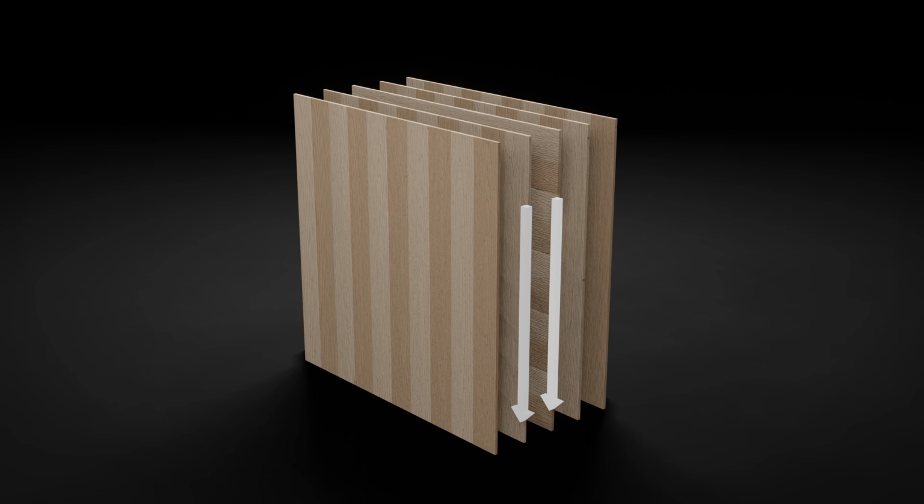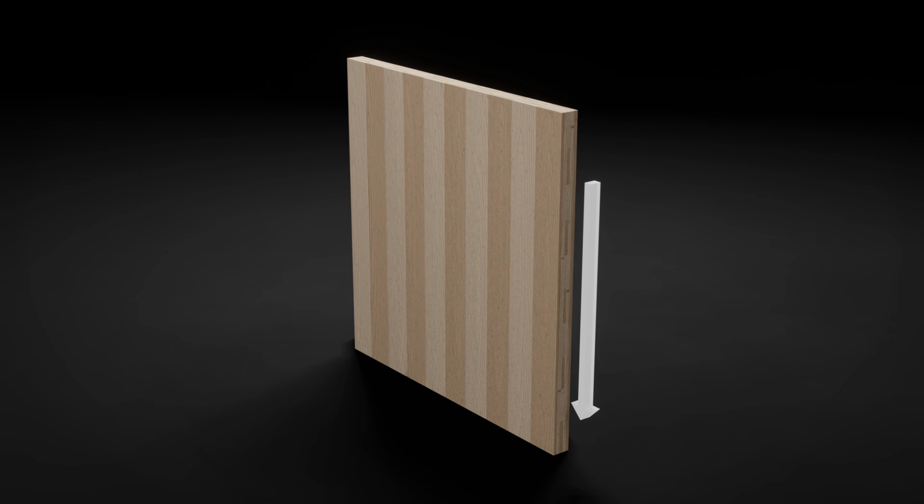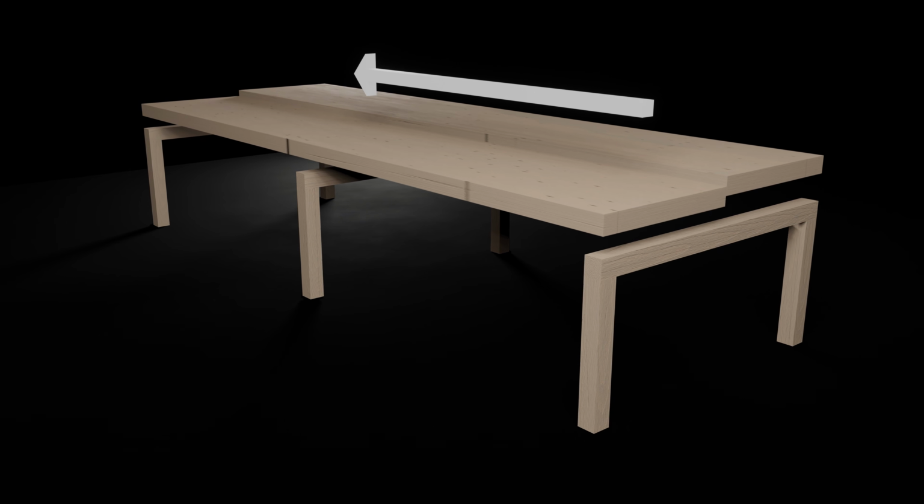For example, the outer two layers of CLT panels can have two parallel layers instead of perpendicular ones. In CLT wall panels, the outer layers are often vertically oriented. This is to optimize for vertical load. Similarly, for roof and floor panels, the outer layers are oriented in the longest spanning direction.